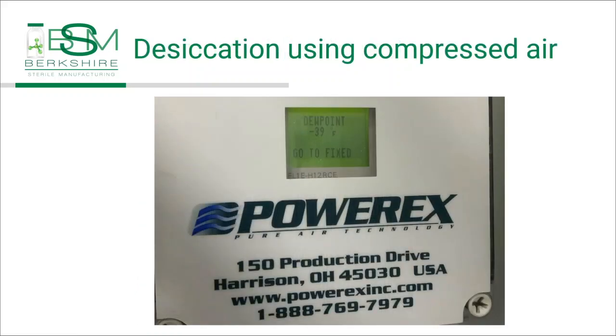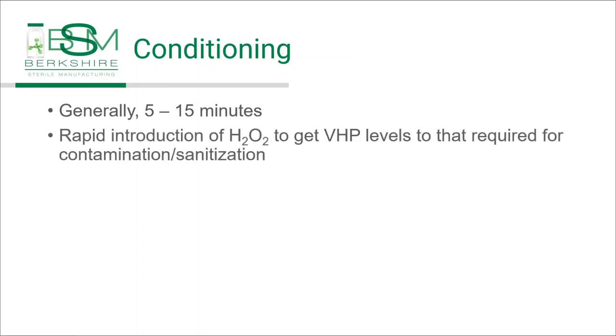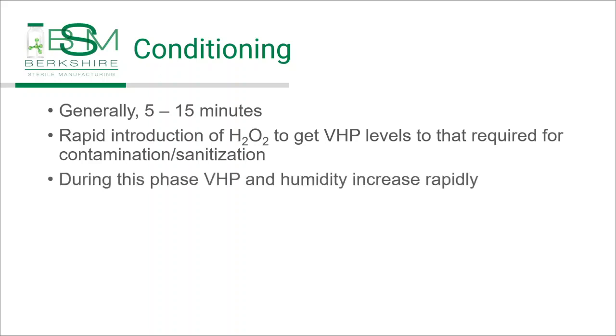And then our larger isolator uses dry compressed air with a dew point of about -40 Fahrenheit in order to dry out the chamber before starting with the conditioning phase. Now, conditioning. Generally, conditioning is 5 to 15 minutes. It's rapid introduction of hydrogen peroxide to get VHP levels to that required for decontamination and sanitization. During this phase, VHP and humidity increase rapidly.